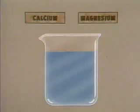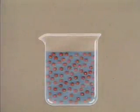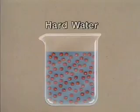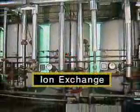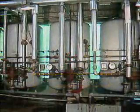Water softeners are designed to remove dissolved solids such as calcium and magnesium salts. When these solids are dissolved in water, they separate into electrically charged particles called hard ions. Water that contains a lot of hard ions is referred to as hard water, and hard water produces scale. Water is softened by a process called ion exchange. In a water softener, hard ions are exchanged for soft ions, such as sodium ions, which normally don't cause scale.